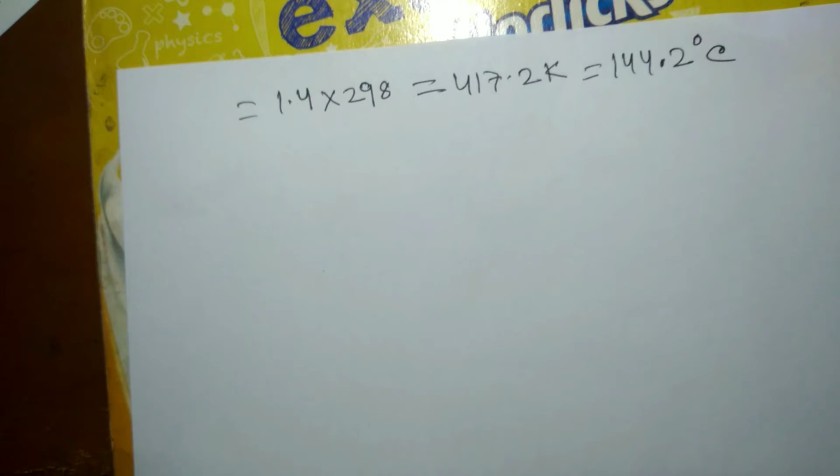The temperature inside the tank or bottle will be equal to gamma, the ratio of specific heats of that fluid, multiplied by the supply line temperature. That formula we can remember, but we can't blindly apply it for every case.